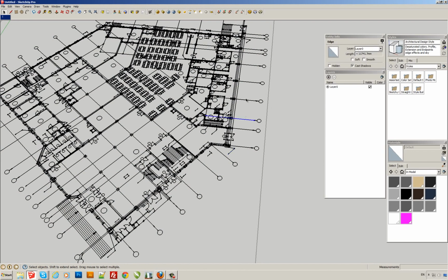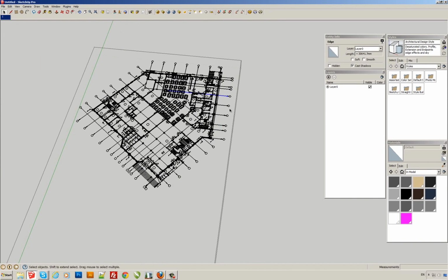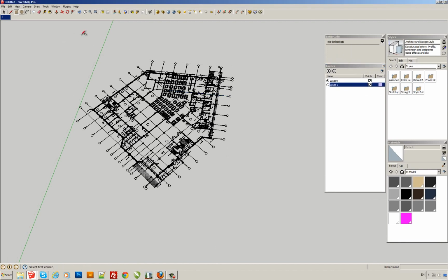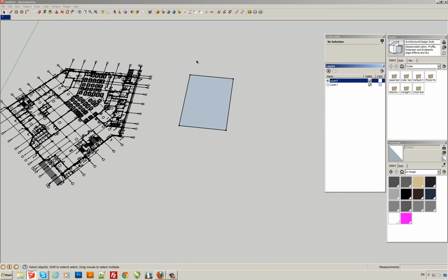So if we choose this separate edge, this badge tells us which material is used on the edge, and we will use this to work around the color by layer feature, because color by layer is just working with the geometry, with the faces, but not with the lines.